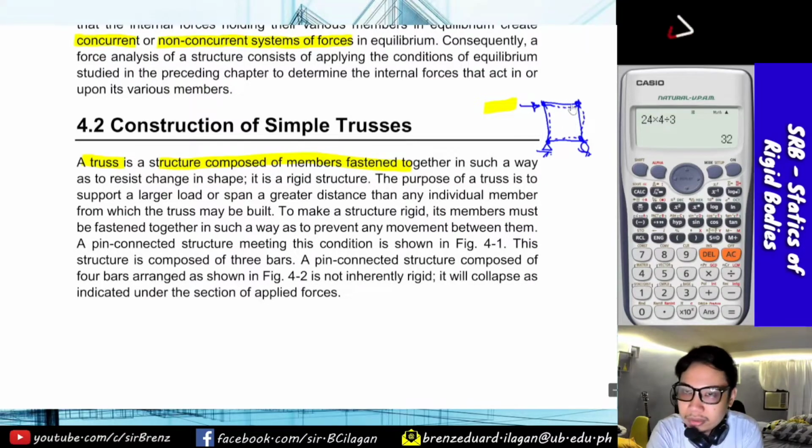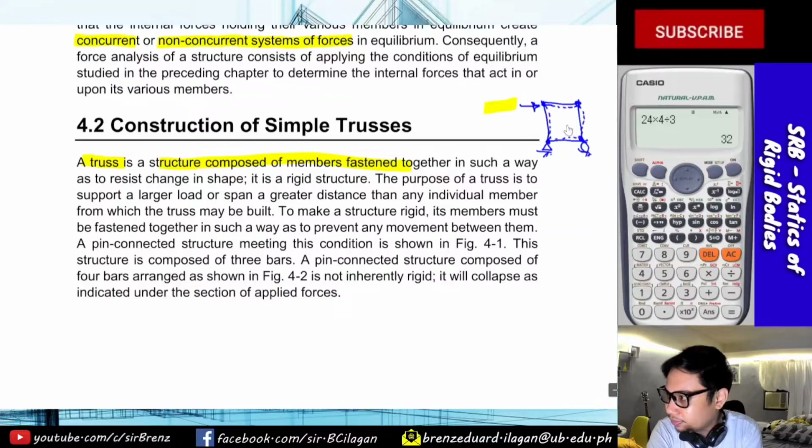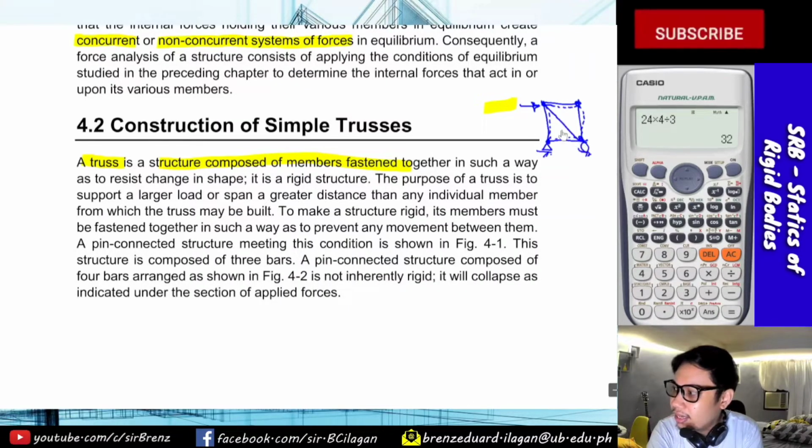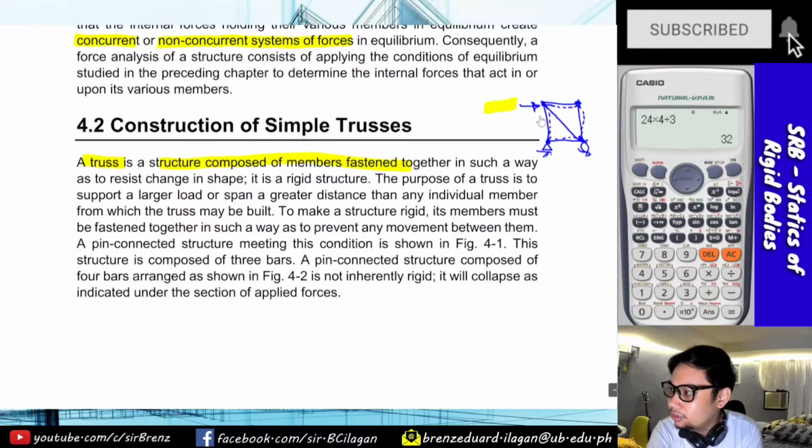So, in order to resist this deformation, or hindi naman exactly deformation, but para maiwasan yung paggalaw nito, naglalagay tayo ng diagonal members. Ayan. So to resist that, lalagay tayo ng ganyan, para ma-resist niya yung paggalaw. So meron ka ditong isang member which will resist this horizontal force, o parang bracing baga. Okay?